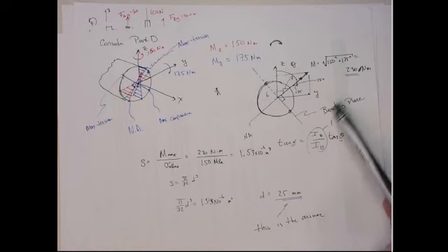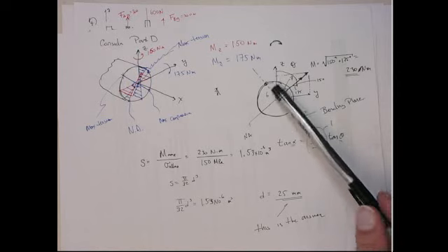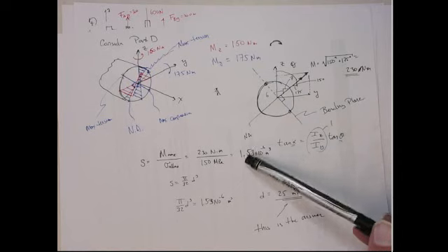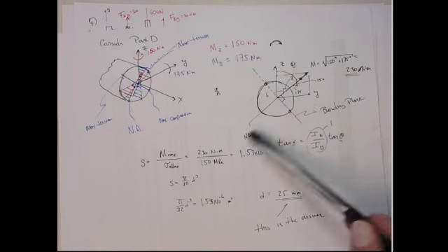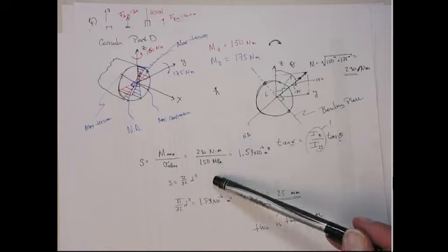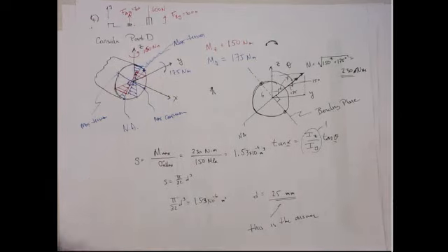So then we can actually treat this just like a regular symmetric bending problem in the bending plane, all right? So the max bending moment at this point is the 230 newton meters. We divide by the allowable stress, that gives us the shape factor that we can solve for D. And obviously, you want to pick the biggest diameter, okay? Although 24 millimeters will work at point A, it doesn't work at point D. All right? So that's the answer.